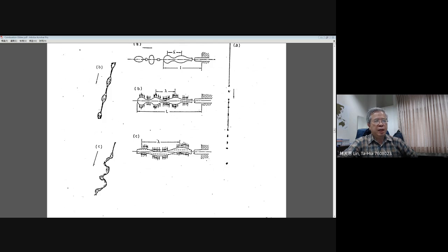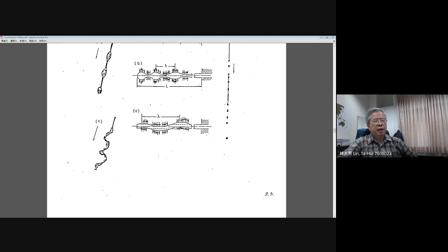Even in the final case, when the velocity is too high, the momentum will push all your liquid out of the injector as so many tiny droplets. That means we go to the atomizing regime.